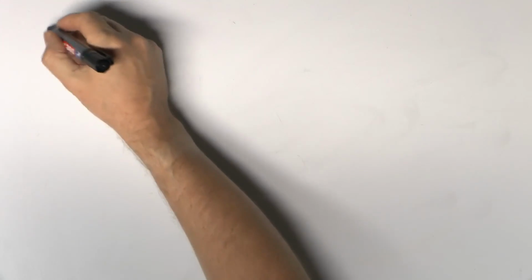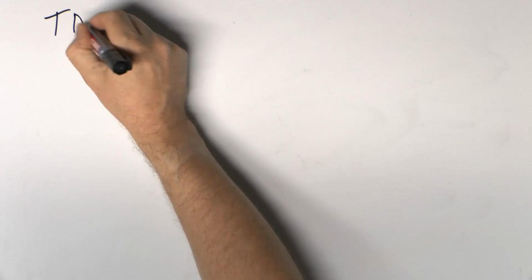Now, for the purposes of this video, and in fact almost all the time in the real world, the type of installation we're going to be talking about here is TNCS, mainly because in the UK and certainly most other places that is the most common type of supply. Certainly in the UK, anything in the last 50 odd years is almost certainly going to be a TNCS. And even things which may look like, say, TNS, probably aren't. They're probably TNCS, either being converted deliberately or just purely by changes to the network.